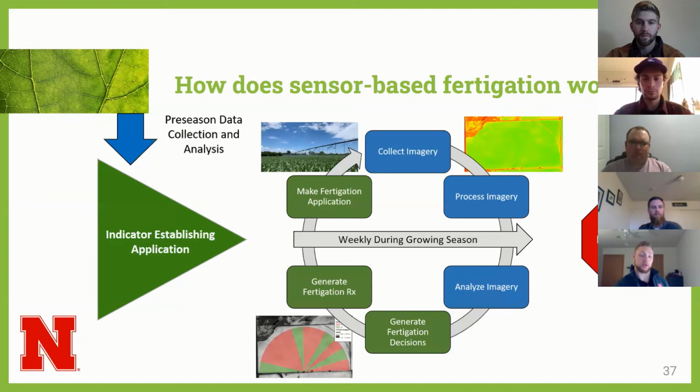We get elevation and slope data, typically using LiDAR, but farm flight is enabling an elevation layer as well, which could be a really good high resolution source. We also get irrigation system specific parameters, like pivot length, pivot center, and flow rate, as well as fertigation system specific parameters, especially if you have a variable rate fertigation pump.